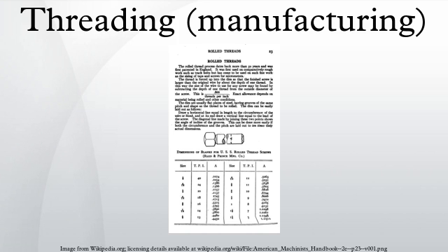There are lobes periodically spaced around the tap that actually do the thread forming as the tap is advanced into a properly sized hole. Since the tap does not produce chips, there is no need to periodically back out the tap to clear away chips, which, in a cutting tap, can jam and break the tap. Thus thread forming is particularly suited to tapping blind holes, which are tougher to tap with a cutting tap due to the chip buildup in the hole.